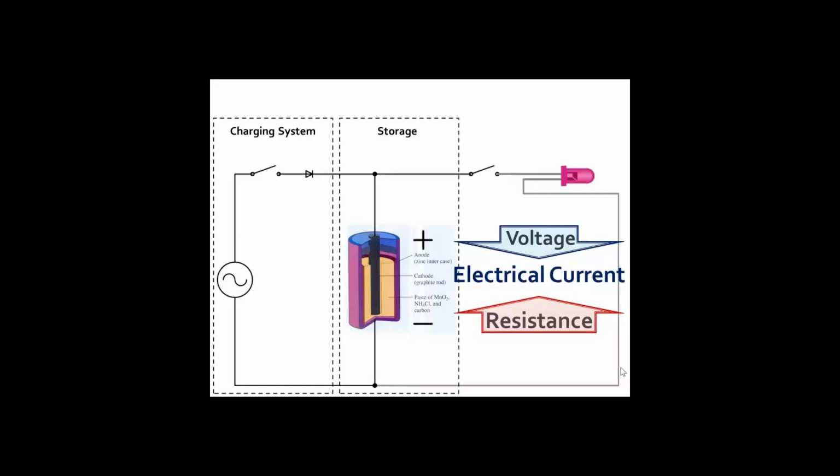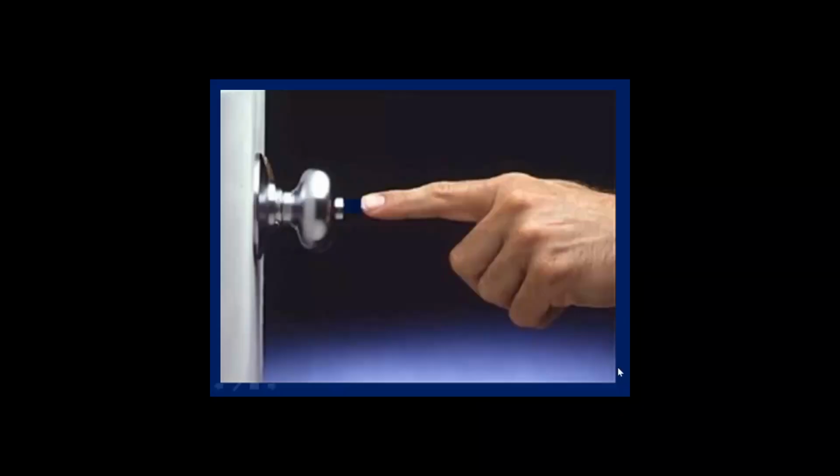But the voltage that's supplied by this cell, when fully charged, gives you about 1.5 volts. At 1.5 volts, that's not enough pressure to make electrons jump across the air gap of an open switch. Now, I said that the electrons can't jump across the air in an open switch, but I said that wasn't always true, but it was true in a circuit where you're limited to 1.5 volts. Let's take a couple other situations here.